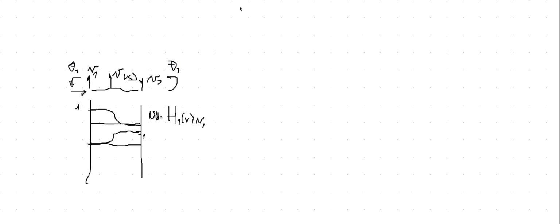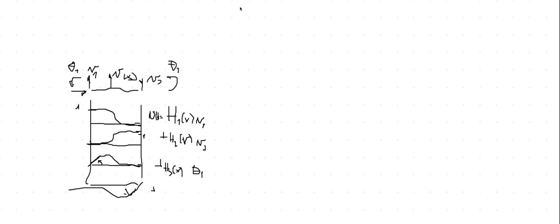So that becomes plus h2 times V2. And then plus, what's also interesting, you have this rotation here, unit value. So this is 1, but displacements are 0, and rotation is 0. So that becomes something like a Hermite polynomial of this kind. That becomes h3 of x times theta 1. And then finally, h4 of x. This is unit rotation here, 0 displacement there, and so on. So you have it like that. So plus h4 of x times theta 2.